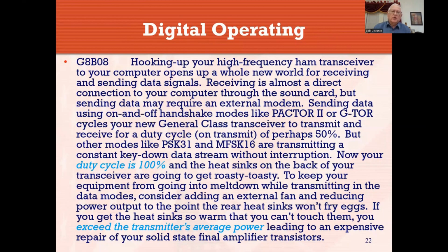Those modes let you transmit and receive for a duty cycle of perhaps 50%. Don't want to push it too hard. Other modes like PSK31 and MFSK16 transmit a constant key-down data stream, so your duty cycle on those modes is 100%. On the PACTOR, it's not. You can use the Class C amplifier because it's not transmitting at a duty cycle of 100%.